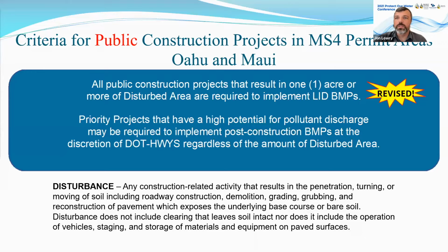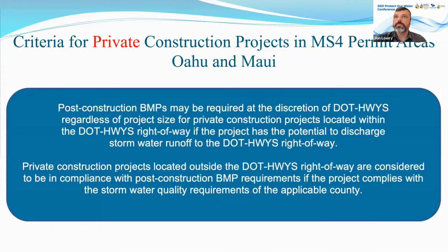We're only talking about disturbed areas being activity that results in the penetration, turning, or moving of soil, including roadway construction, demolition, grading, grubbing, reconstruction of pavement which exposes the underlying base course. So if you're just doing a grind and overlay, you're not considered disturbing unless you get all the way down to base course.